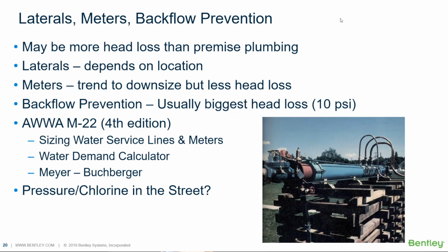This past year, we were supposed to have a joint session at the AWWA NFPA conference discussing this and how hard it is to get that boundary condition for these models. What is the pressure in the street? And also, if you're doing water quality modeling, what is the chlorine concentration? So we had a whole session to talk about the issues and how this isn't really a trivial issue.